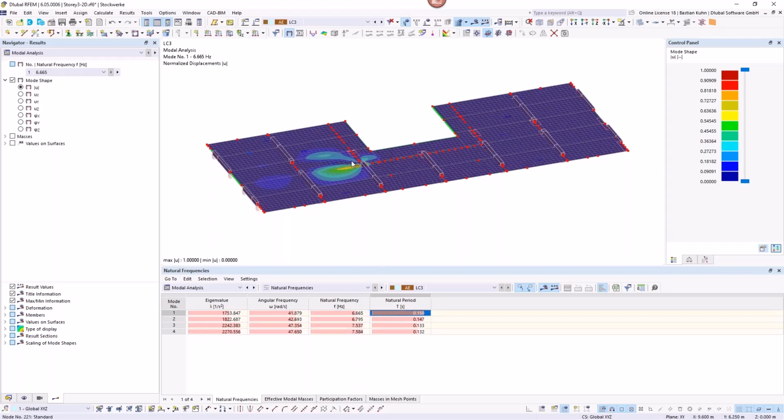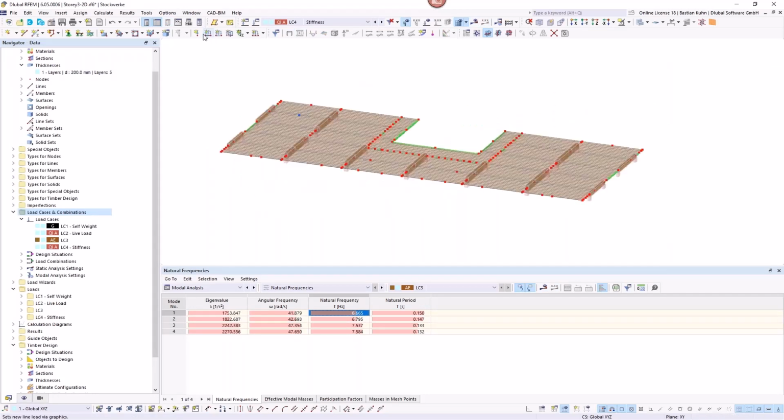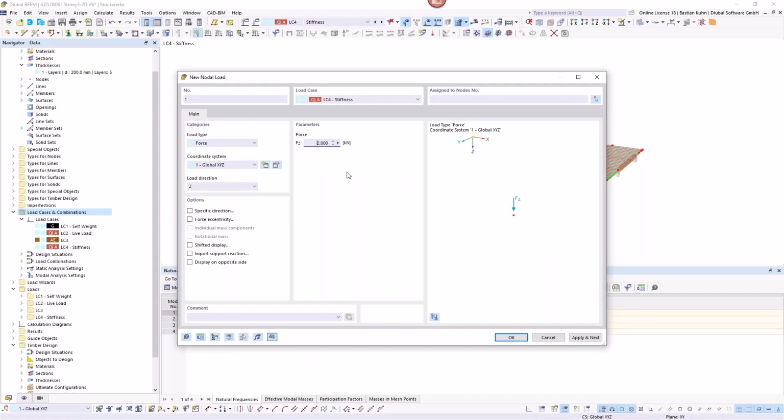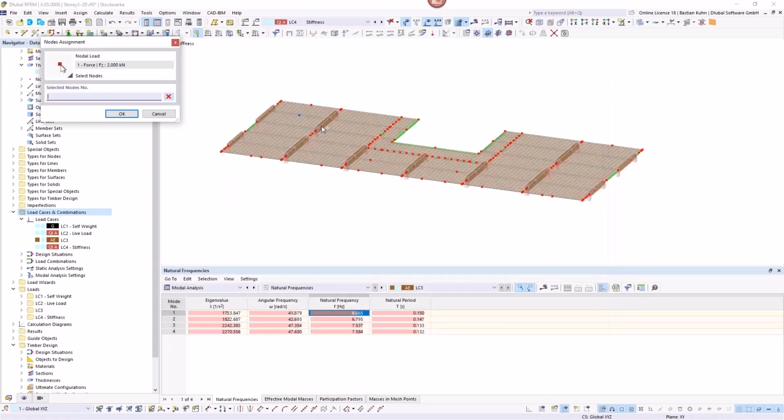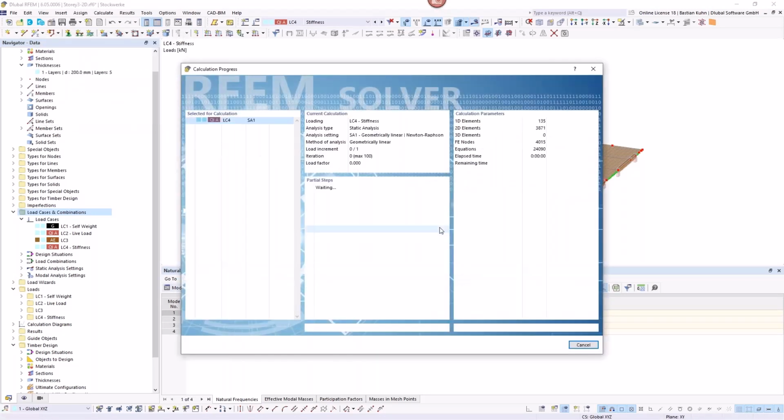You can either make it stiffer, but it's not really in this problematic part. It's more in this part here where you can try to arrange something. But if you argue, okay, I maybe have a dependent area here, it is fulfilled here. At least it is not 44.8% overloaded. And now the second criterion is the stiffness criterion. Therefore, in the maximally deformed part, you have to define a single force of 2 kilonewton, and it should be below the deformation level of 1 millimeter. And when this is fulfilled, your verification is done.